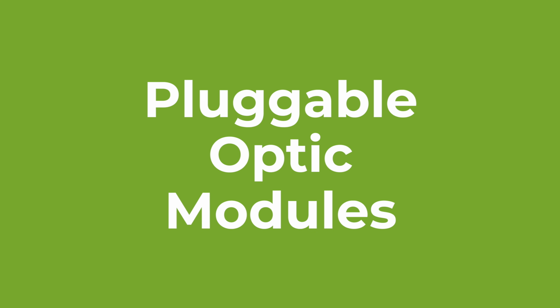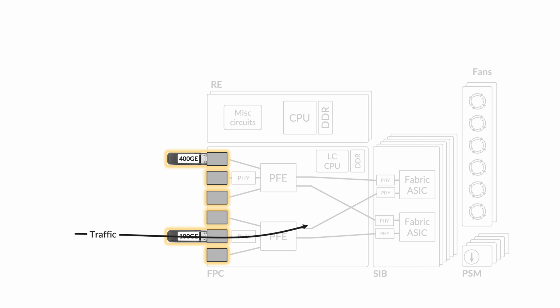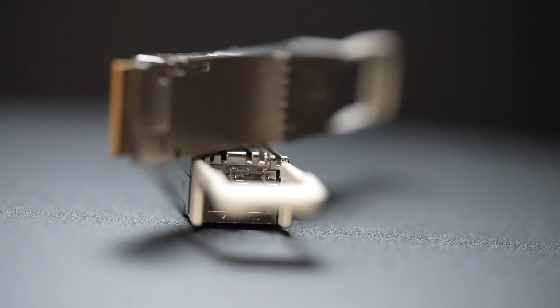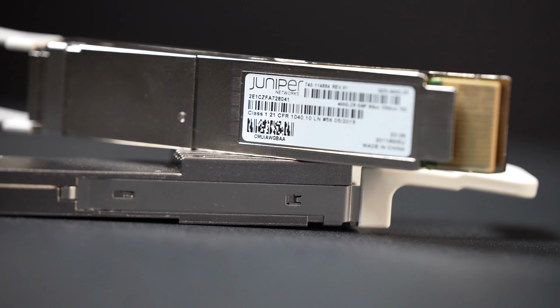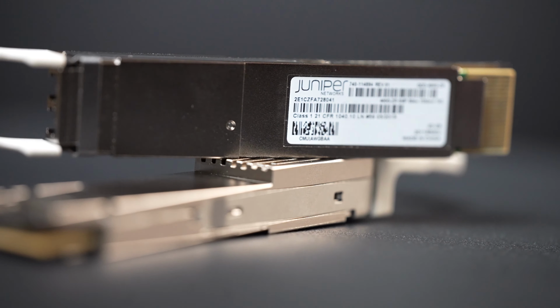And talking about optics, of course their power usage will depend on multiple factors. 100G SR4 will not consume the same amount of energy as 800G ZR. So the speed, type and reach are of course parameters. The question of the influence of the amount of traffic going through the optic is an interesting one. If the module does not do a lot of signal treatment, it will not be a significant parameter. But of course, for a coherent optic containing a DSP performing advanced error correction, it will become an important influence on the power usage.